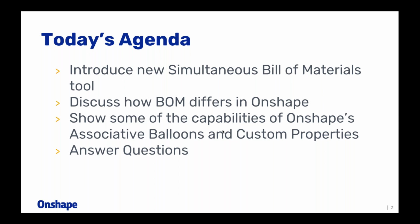But then I want to get into some of the capabilities of the associative balloons in drawings and custom properties. Because I think a lot of users out there are familiar with the concept of associative balloons, meaning I tag a part in my drawing with a balloon, and the balloon is linked to the item number in the bill of materials, right? But it's more than that. You can do things like link the balloon to the part number, for instance. So if you don't want to show item numbers linked to a BOM, but you'd rather show part numbers, you can do that in the balloon option. So there's lots of little details that I want to go over that surround this topic of the custom properties and balloons at the assembly level drawing.